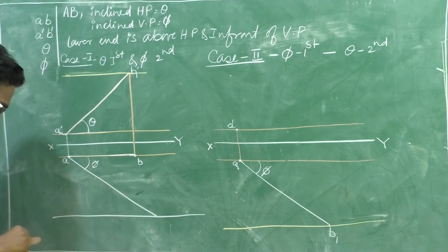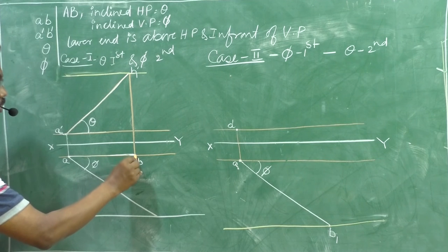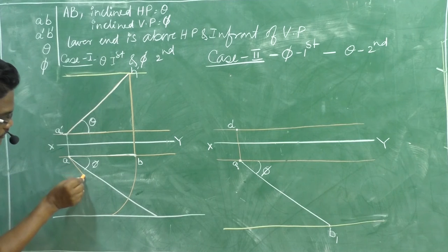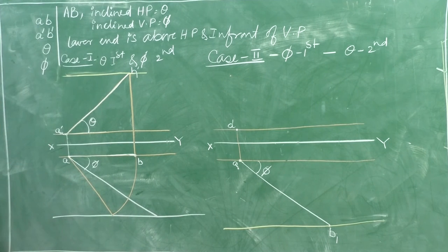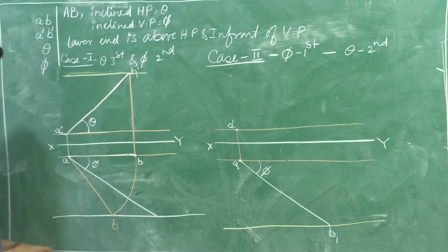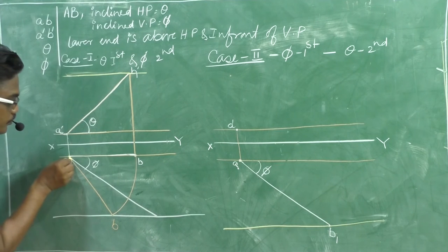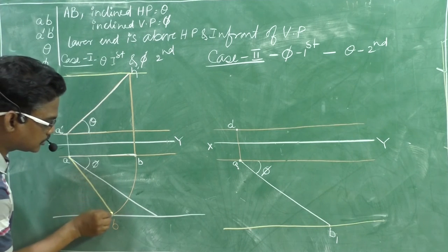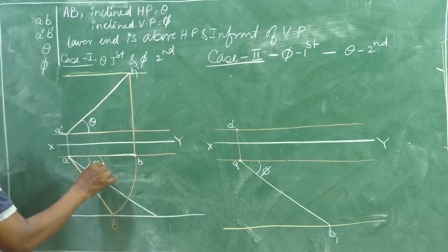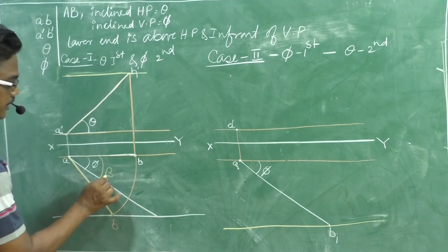Therefore, we need to rotate like this. Okay? Right. This is the required top view. This is AB. This is the required top view. I want to show it with yellow. Required top view. And if you see the angle of inclination, this is more than phi. And that is the reason this is called the apparent angle. We can call this beta.